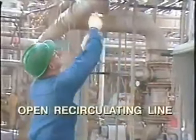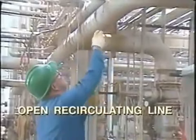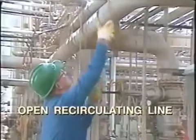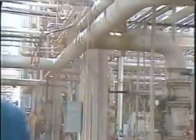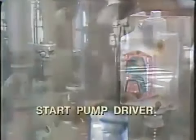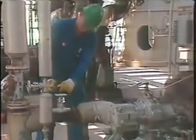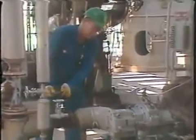Some pumps are equipped with a recirculating line that recirculates liquid from the discharge back into the suction line. The circulating line should be opened before the driver is started to prevent operating the pump against dead shutoff. Now start the motor, or if the pump is driven by a steam turbine, start the turbine following standard practice recommended by the manufacturer and your operating instructions and procedures.